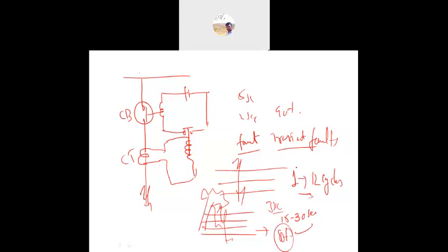So there is the first reclose, second reclose, and third reclose. If a transient occurs for 3 seconds and the arc extinguishes, then once the fault is cleared, it will automatically reclose. If the fault is not cleared, it will open again. That is the second shot, and similarly there is a third. Each reclosing has its own time.